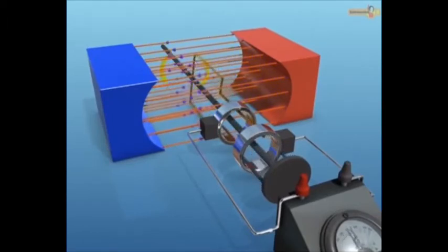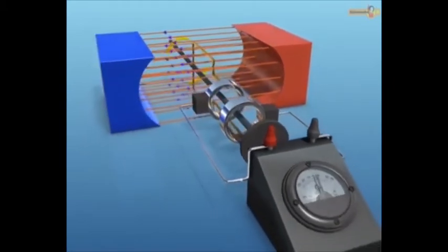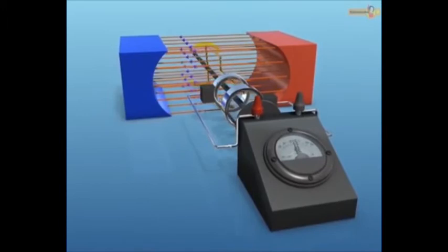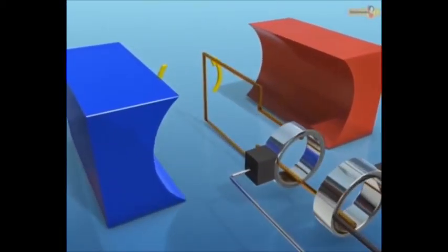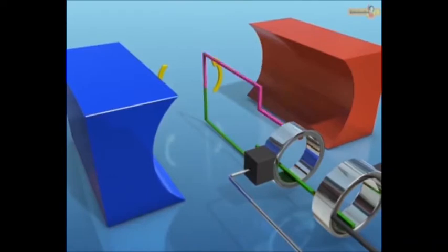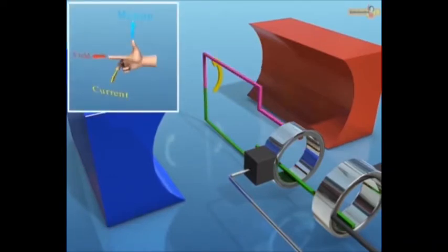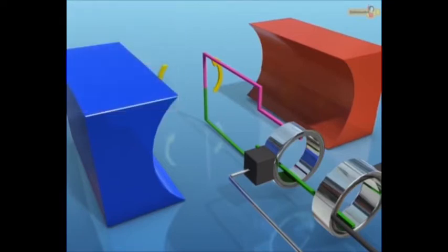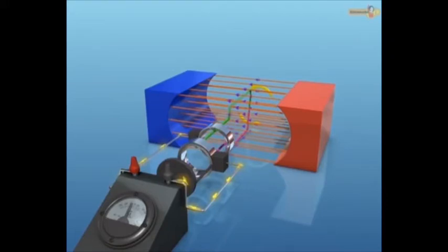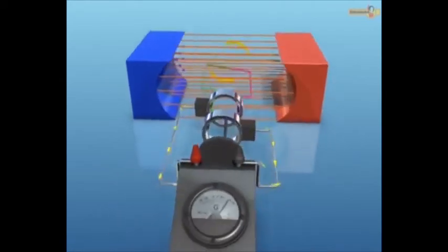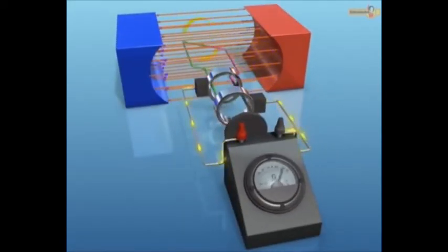Due to change in the relative position of the armature coil, the direction of the current flowing in each arm of the armature coil keeps on changing, and hence the current so obtained is alternating current. To understand the generation of alternating current more clearly, let us mark one arm of the armature as green and the other as pink. As per Fleming's right-hand rule, the direction of current in the arm marked green is outward, and in the arm marked pink is inward. After rotating half a turn in the anti-clockwise direction, the direction of current in the green arm becomes inward and that in the pink arm becomes outward. Thus, after every half turn, the direction of current changes, and as a result, alternating current is generated.